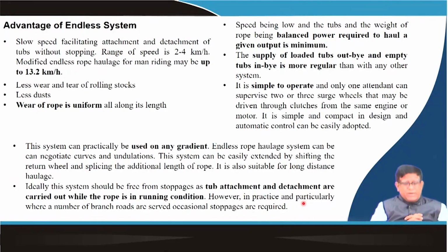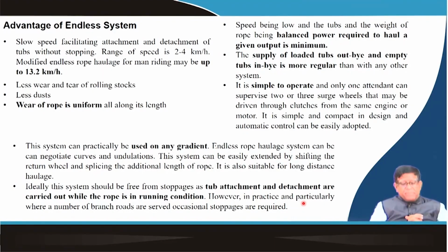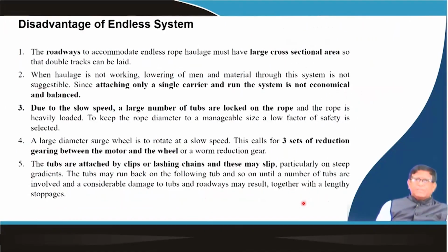This is also an advantage of this system, and it is free from stoppages, because the endless rope will keep on moving, and your attachments and detachments have to be carried out while the rope is moving. So when it was introduced, it was found that its productivity is more than both the other types of rope haulage system.